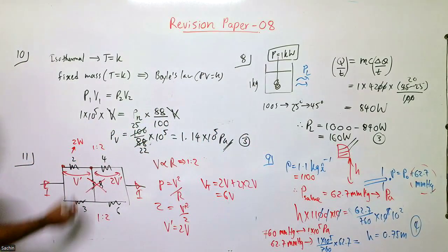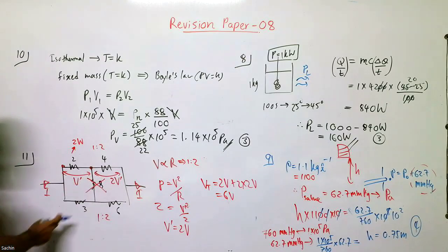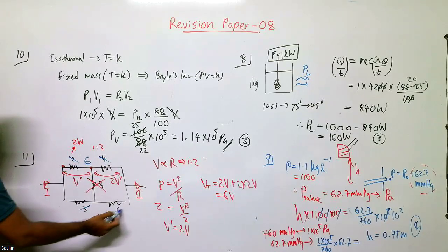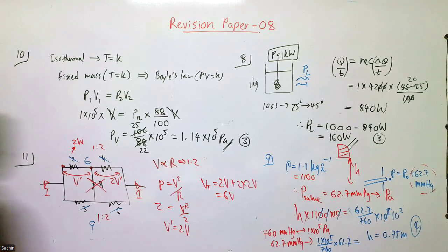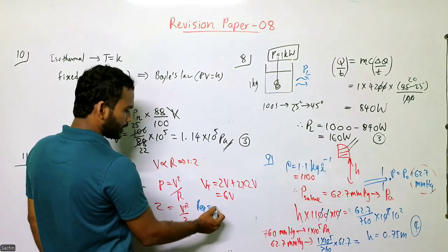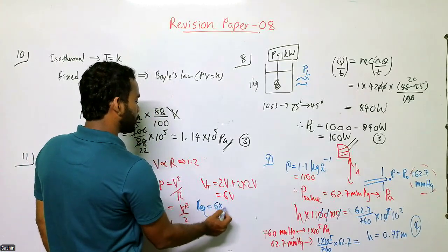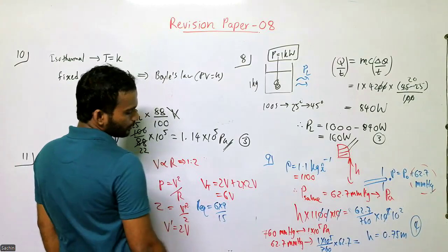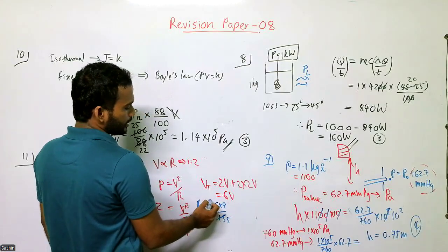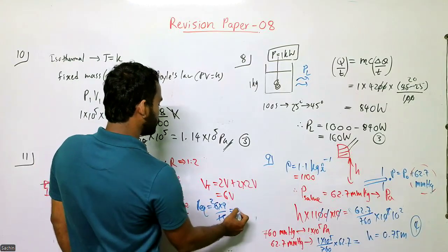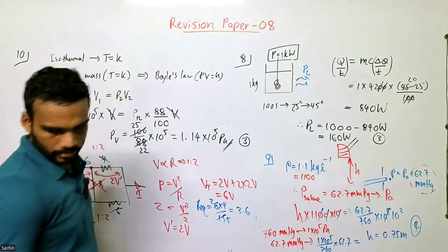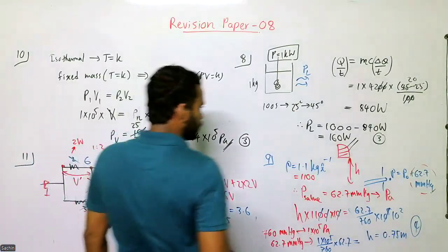It is again a simple thing. So now after removing this middle path, consider the Wheatstone bridge. This path will have 6 ohm resistance. Here it will have 9. So what should be the equivalent value? Simply, the equivalent value you can calculate when two resistors are in parallel. It should be the product divided by the sum. Product divided by the sum. Here it is 54 over 15, which equals 3.6. Okay, so now you got all what you require.